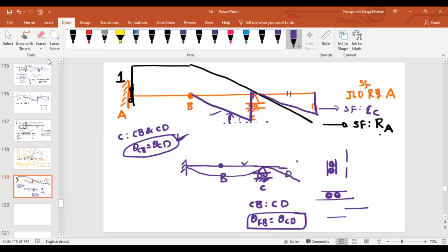If I draw the ILD for the right side, then it becomes a zero slope, sir. Am I right? Yes, it becomes zero slope. Why? Because if I draw the right side of C, the diagram looks like this: if I place a vertical shear hinge here, then as you can see, this simply tilts upward. Okay, sir, now I understand.